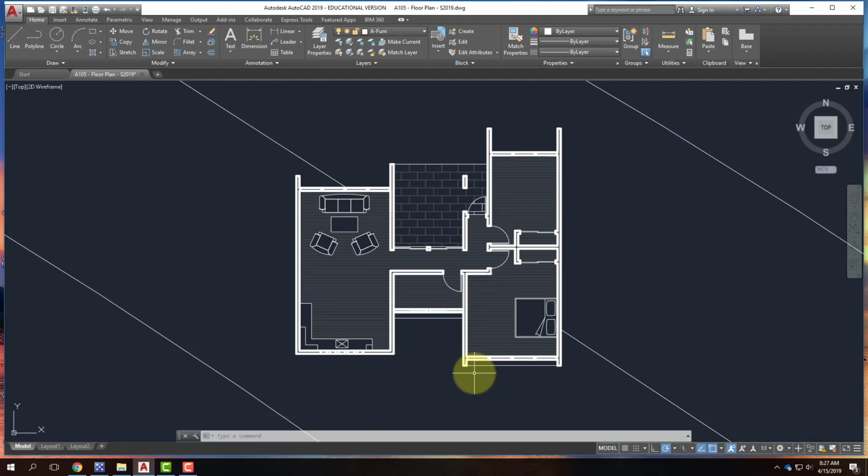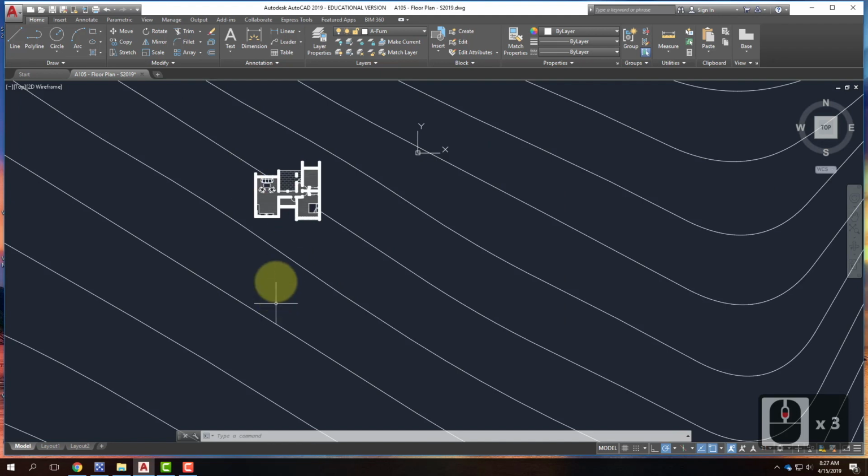And so this is going to be a big challenge for a lot of you because you've spent the time figuring out what the floor plan looks like and what the orientation of the rooms looks like. And now it's time to figure out what does the space feel like? How tall are the ceilings? And what does it look like from the outside? And so we're going to start with the south elevation, which is the elevation directly below this drawing. And so typically when somebody's working on these elevations, and you probably did this in 130, we start to fold out our elevations.